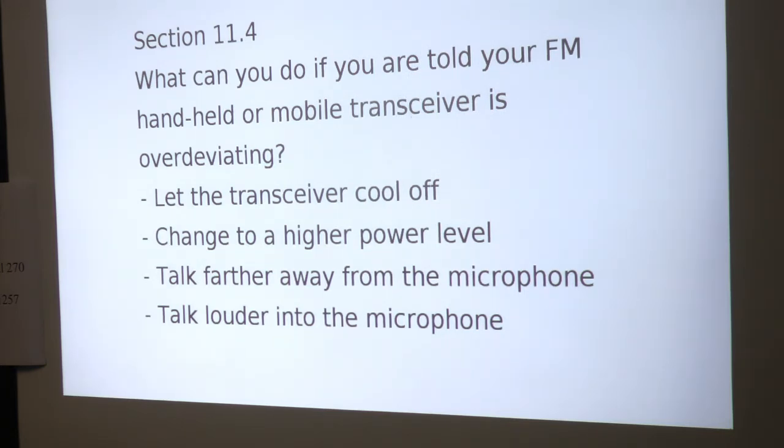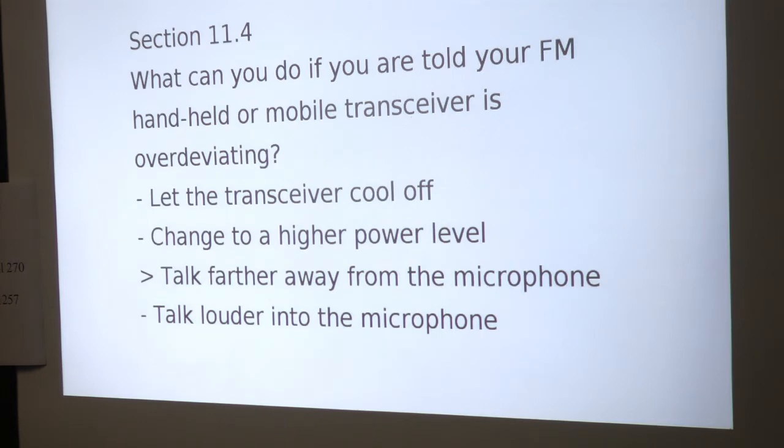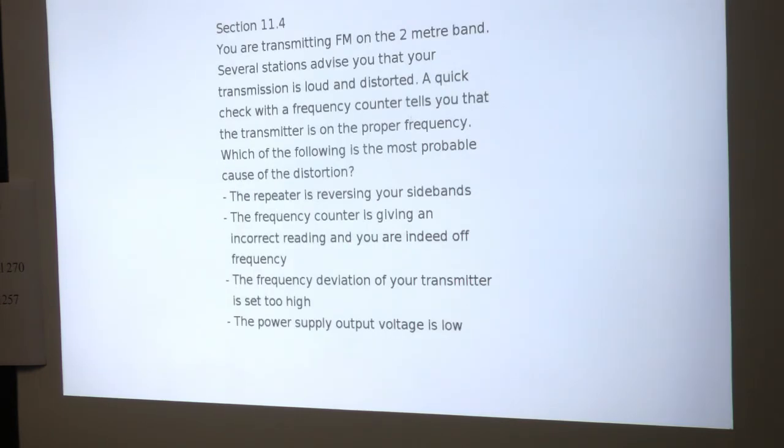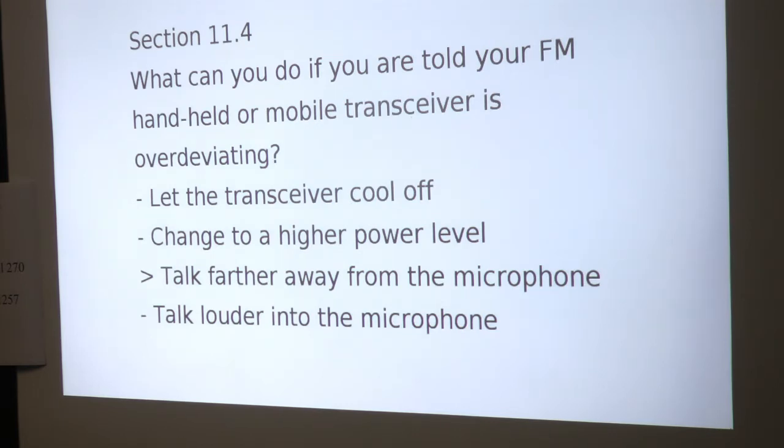Let the transceiver cool off. I would say number 3. Talk farther away from the microphone. That's correct. Or turn down the gain is another thing you can do. So, taking 4, talk louder into the microphone? Yeah, makes sense. Can you hear me now?